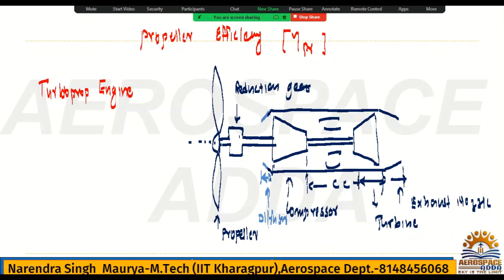Also, turbofan is now used in 90% of commercial aircraft because of that good feature: both supersonic and subsonic are possible. Both are possible in the case of turbojet also, but turbojet at subsonic speed and low altitude will not give good performance. That I had explained.